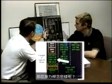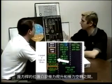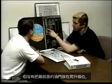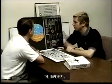And what about THRUST LEVER? THRUST LEVER kind of falls in between THRUST CLIMB and THRUST IDLE. What's going on is THRUST CLIMB has been commanded, but instead of having the most forward throttle in the climb detent, the most forward throttle is after the climb detent, which is limiting the thrust that's available.